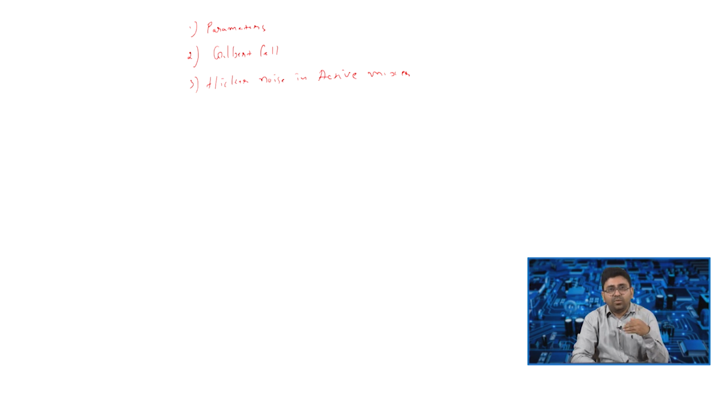where we tried to understand the current mode mixer with quadrature configuration, and how the duty cycle of the LO impacts the conversion gain. We understood the design of the transimpedance amplifier and the importance of the TIA in designing the complete receiver configuration, how the impedance transformation happens, and gradually we tried to see how this passive mixer helps us to design a receiver.